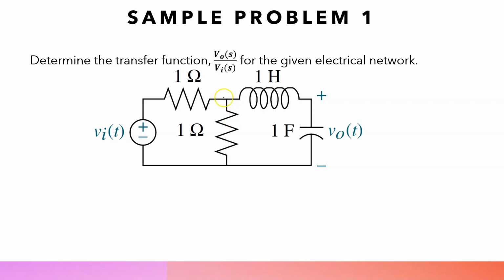If you see the circuit, it is given in terms of t, in the time domain, but the question asks you to determine it in the s domain, which is the frequency domain. So you can do this using the Laplace transform. If we analyze the circuit, we can apply Kirchhoff's voltage law to determine the equations that represent this circuit.